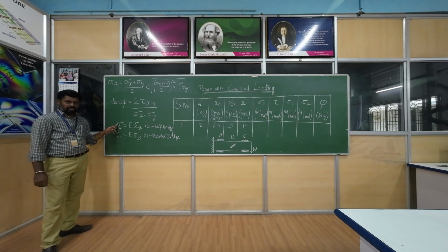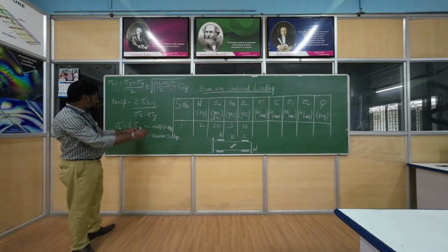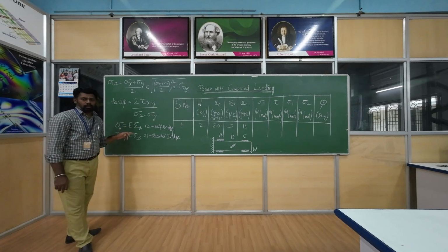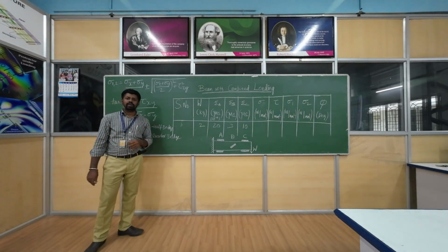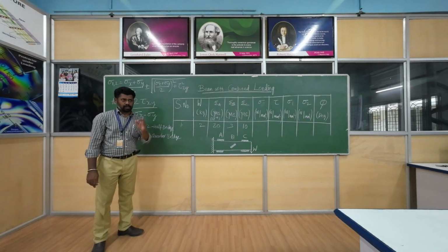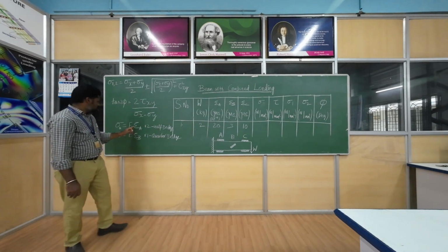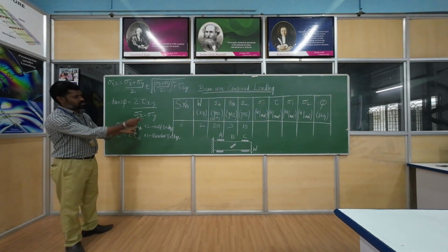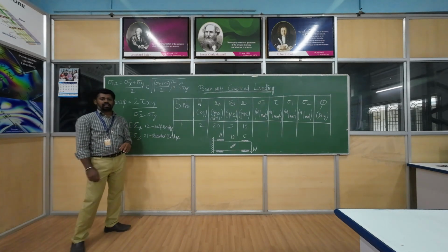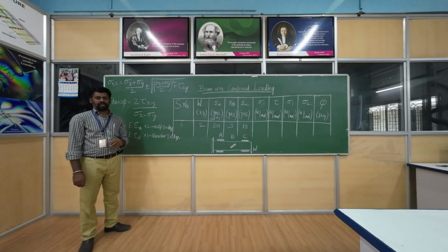So we want the stress. We already know the strain at section A, and we know the metal property. The Young's modulus of the given beam is 70 gigapascal, since it is made of aluminum. So 70 gigapascal times the strain will give the normal stress at section A.